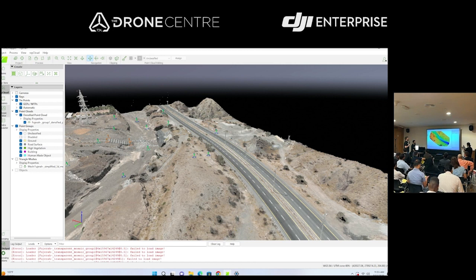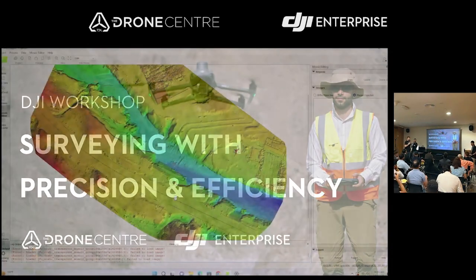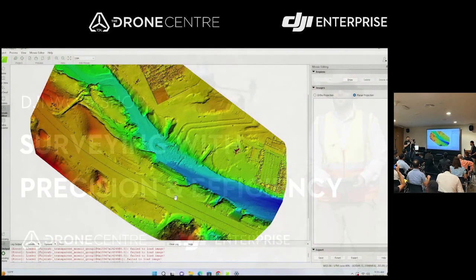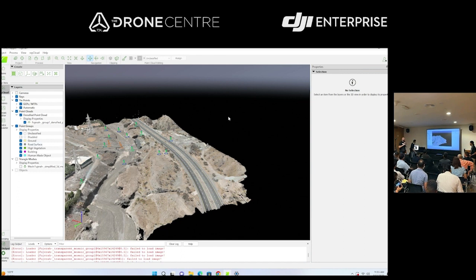Here we can see at 215, here 230, like 15 meters in the wadi area. And this is fine, you don't have to use that feature, and you have good data. You take it from the road, so 120 above the area. Remember, terrain follow is an option you can select, or deselect if you're not happy. And there may be too many variations, maybe because of the power lines.